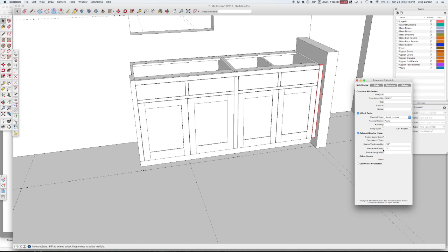But basically, what this width is adding is a scribe. So since this is a wall style, I want to build it not with a 1.5 inch wide style, but a 2 inch wide style. I don't want to draw it here as a 2 inch wide style, but on my cut list, I want to make sure that extra 1/2 inch is added. So that's what you get with a wall style.